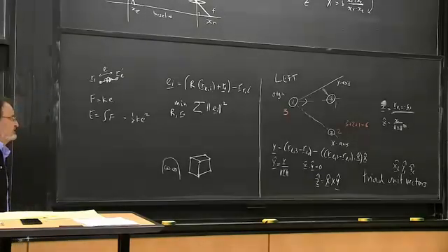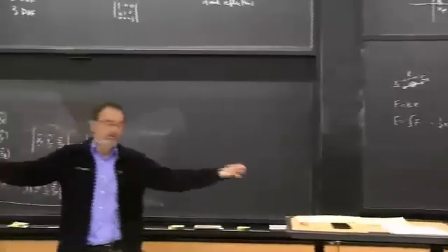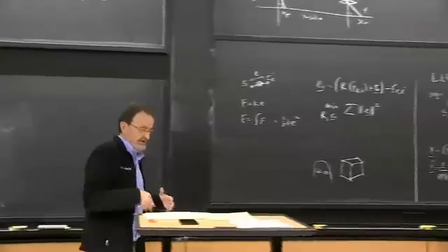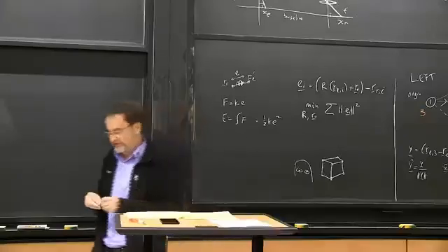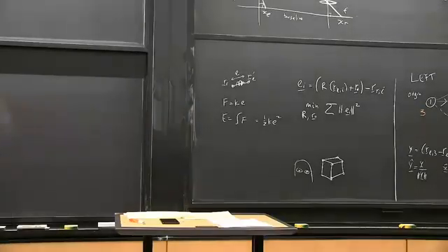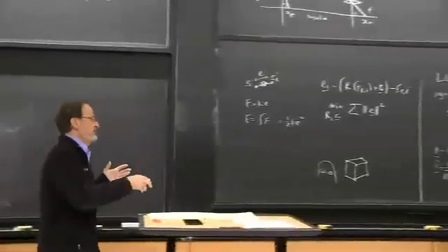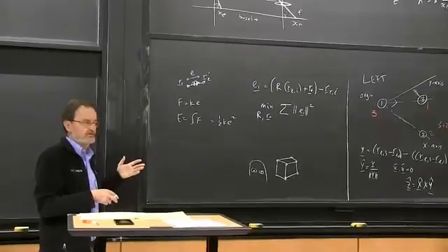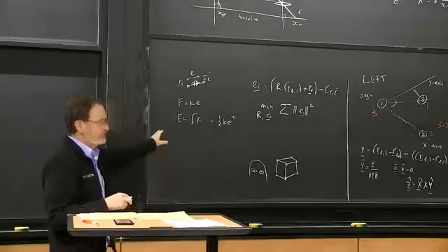Now, in practice also, we might be inclined to measure more than 3 correspondences. If we have these 2 LiDARs on the vehicle, they're giving us hundreds of points, and there will be some error in all of those measurements. But again, as we noted, if you have lots of points, least squares or some other method can dramatically improve your accuracy, if you can make use of all of those correspondences. So this just uses 3 points. And yeah, you could now repeat it, picking 3 other points, and do that lots of different ways and averaging, and that would be better, but it would be kludgy, ad hoc. So, okay, so ad hoc method number 1.